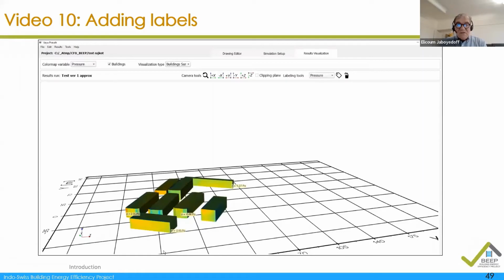And you can think of planning in more detail if you want to go for a kind of building which is, as per a conventional approach, windward, leeward. That means the wind is pushing through. Or if you want to have the wind passing along the facade and try to catch it. Or again, if you want to see on the roof whether you have a chance to have a negative pressure to have some suction effect.